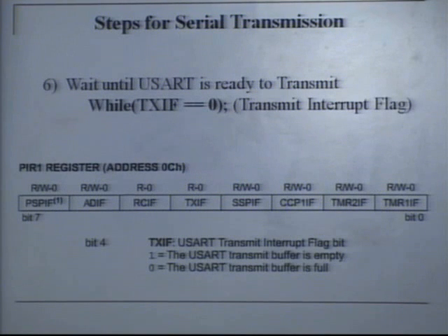Next step, what is the next step? So now we have done all your initial configuration. Next we are going to transmit. So this was a program for continuous transmission of a character A. I am showing you the steps for continuous transmission of A, for transmission of a single character. So now I had completed all my initial setting. Next I need to transmit a character. Before transmitting a character, what should I do? I need to check whether USART is busy with transmitting some other data.